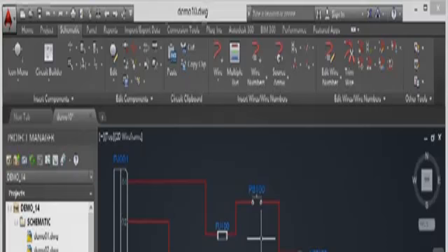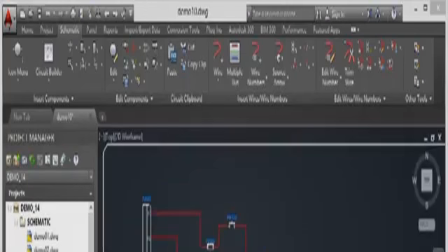We're staying in the project Demo 14 and we're in the schematic subfolder, and we're still in the drawing demo10.dwg. I've zoomed out slightly so that we can see our point-to-point wiring diagram. And what we're going to look at now are the benefits of circuits in your AutoCAD Electrical drawings. Now, I've created that basic circuit as a point-to-point wiring diagram, and what we're going to do is save that circuit as what is known as a W block.